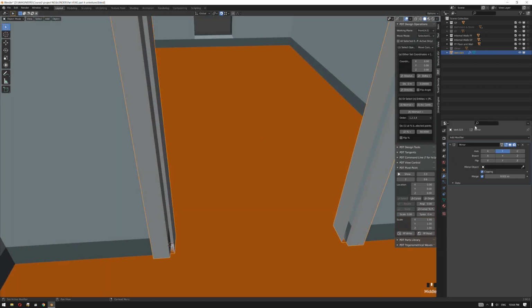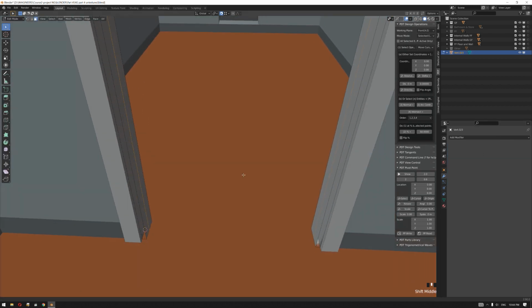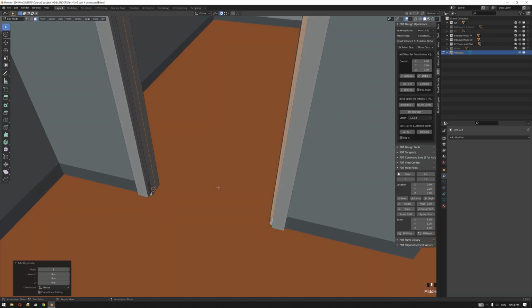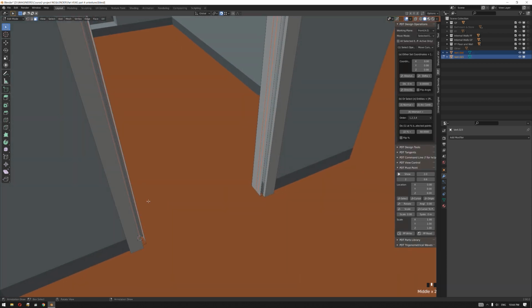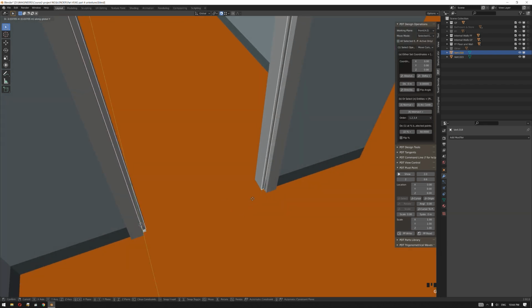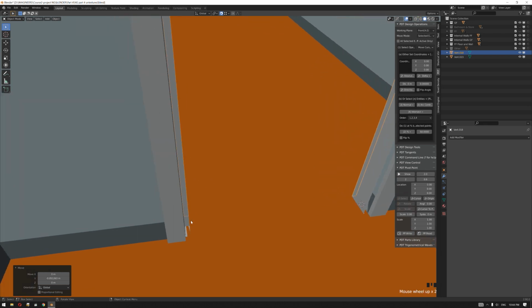Okay, so next we're gonna need to close this frame, so I'm gonna apply the mirror modifier. First let's go outside the edit mode, apply, let's select these faces, Shift D, or we can go into separate mode immediately, so P to separate that selection and make sure we are selecting them, and G on the y-axis using the snap, we can snap them to this part.